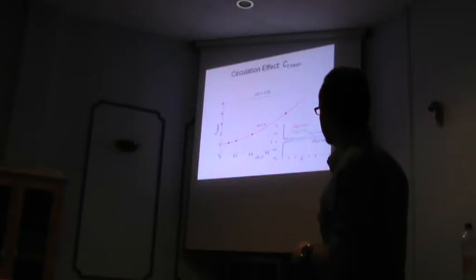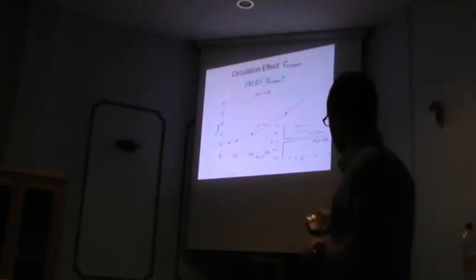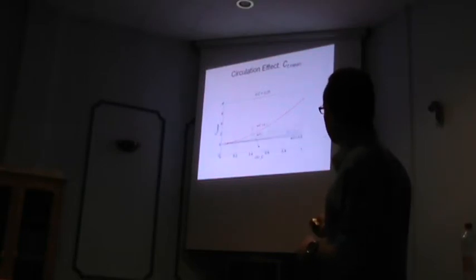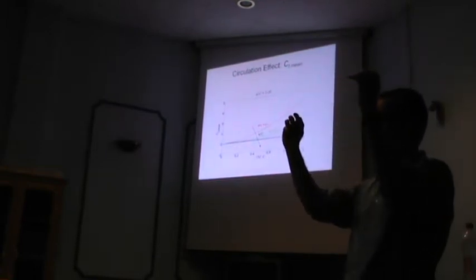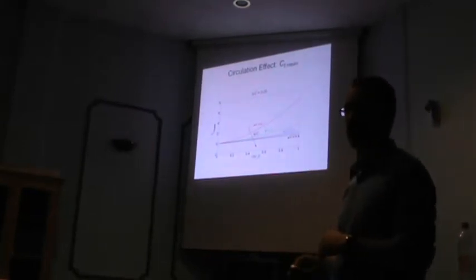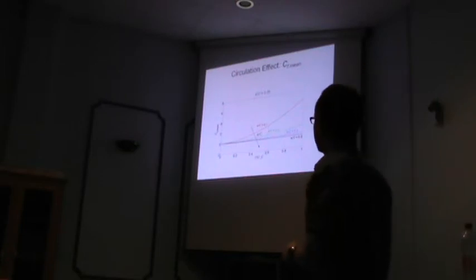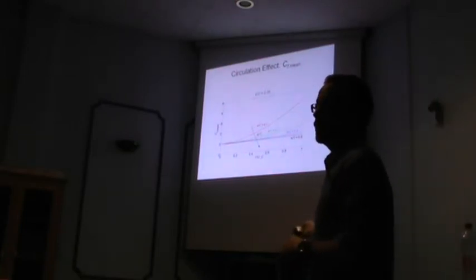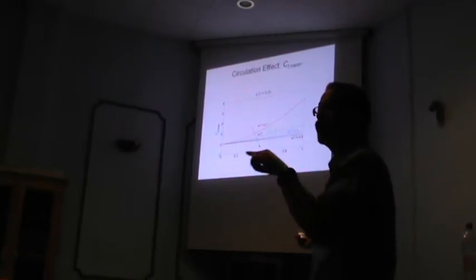Now, if you do this calculation, however, for a different wavelength, then you see that as the wavelength increases, so the spacing between the vortex structures becomes longer and longer, in fact that CF goes down for the same circulation. So in that sense, longer wavelengths are not good for the production of thrust for the same circulation. Now, remember, all of this is in fact for just the CF mean. Ultimately, we care about the full CF.